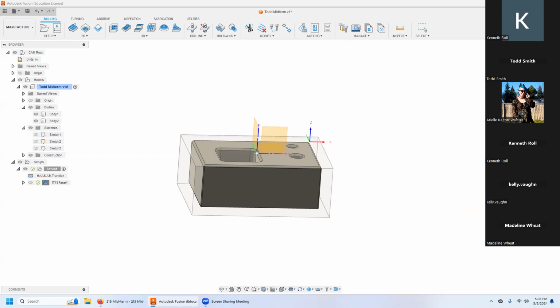I could change the step over, but it's very frustrating. We'll do that when we use a 1/2 inch end mill, and you can see some of my frustration with this. I want a finishing step. And I want it to slow down to an 80 for a nice pretty feed. That last step down, I'm going to set that for 20 thou.